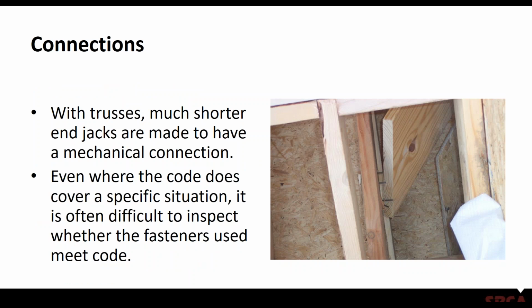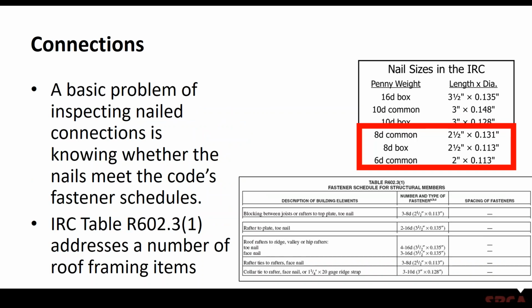Certainly this connection, where I've got some type of valley tying into another bearing location. Fortunately, they didn't do a very good job of cutting that member either, so now you're trying to support that off some nails where obviously there are gaps. You're not getting the full nail penetration on some of those nails, and that's just not a very good situation.